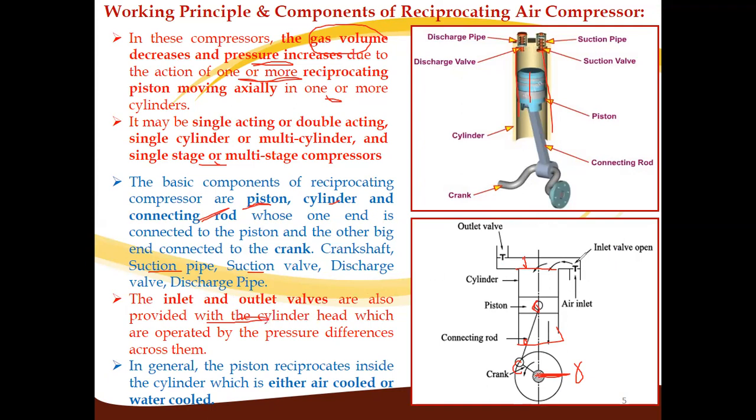If the pressure is atmospheric, it will open the suction valve, and if the pressure is above atmospheric pressure, it will open the outlet valve or discharge valve. So because of the pressure difference between these two valves, the inlet valve and outlet valve, the two valves get operated.